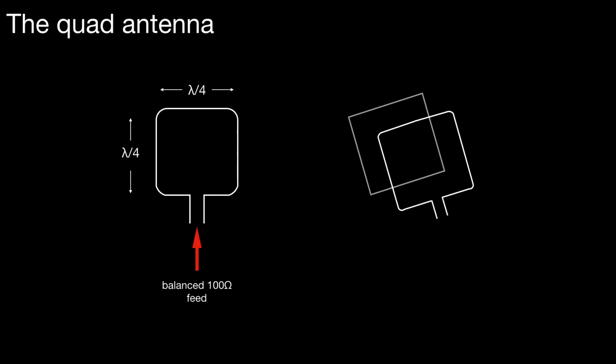If we put a reflector behind the quad, in the same way as we do with a yagi antenna, then the reflector once again would be approximately 5% longer on each side, and the effect of the reflector would be to reduce the impedance down to about 75 ohms. So this goes back to the point about adding other elements to an antenna, such as a quad or yagi. The general effect is to reduce the feed impedance.